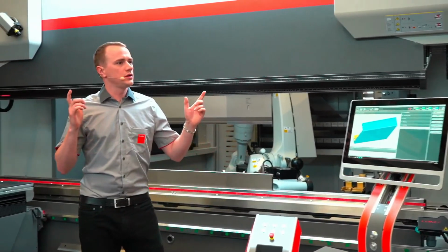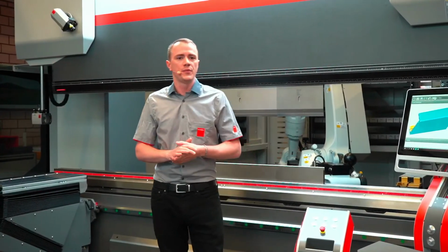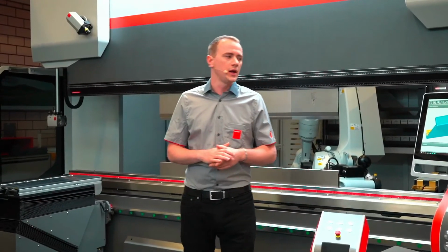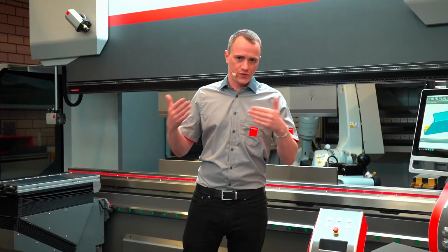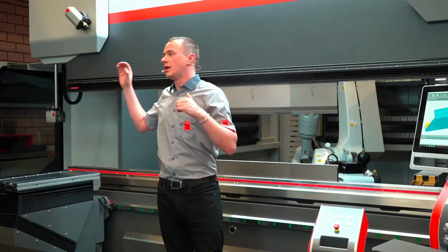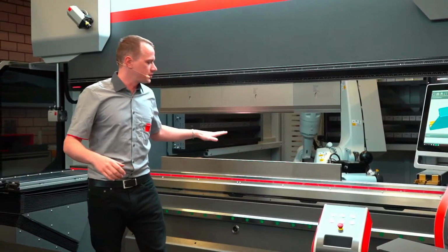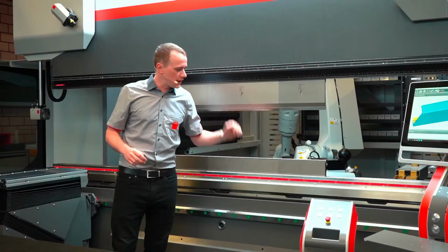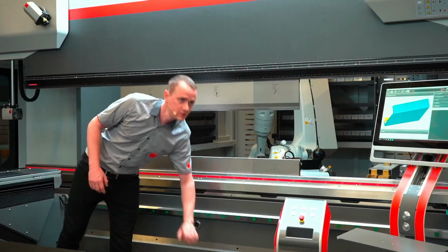How we measure how much we need to compensate is pretty simple. We have pressure sensors in the upper cylinders of the press brake, and the machine notices the pressure and the force it needs to physically bend the part, and therefore can compensate the C deformation and also the bottom deformation. So it will over travel the calculated position, and it will also push the center upwards with the hydraulic cylinders here in the bottom.